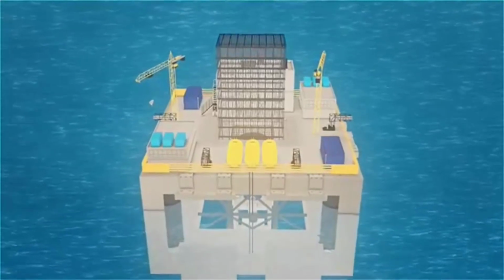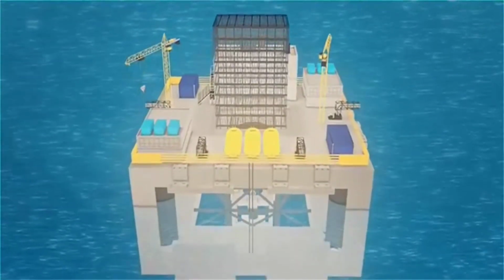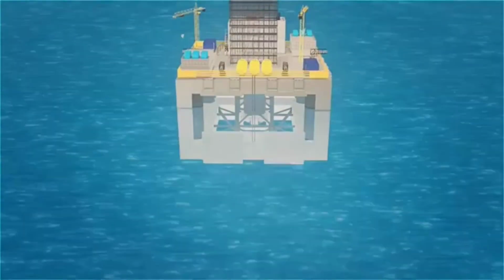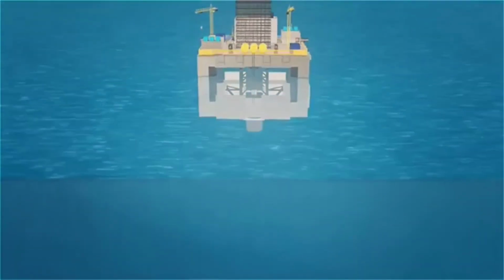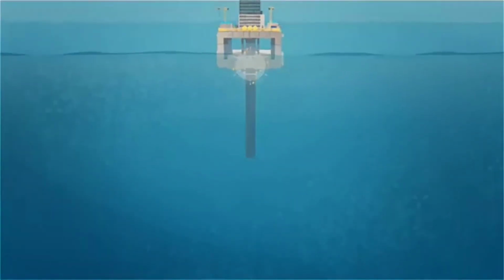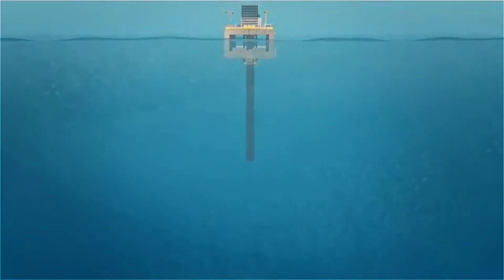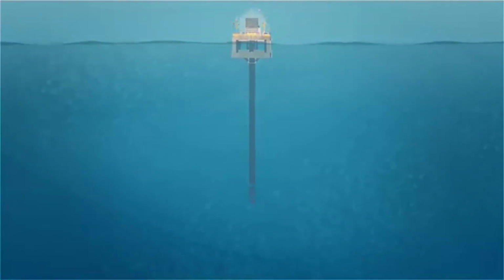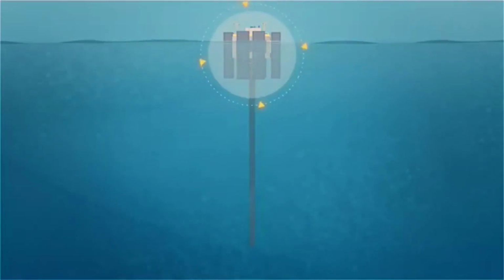A Lockheed Martin Corporation-led team of subcontractors has designed a 100-megawatt OTEC system capable of fabricating the 1,000-meter cold water pipe, or CWP, directly from the platform. Once the cold water pipe is completed, the fabrication facility is removed and the power modules containing the seawater pumps and heat exchangers are installed.